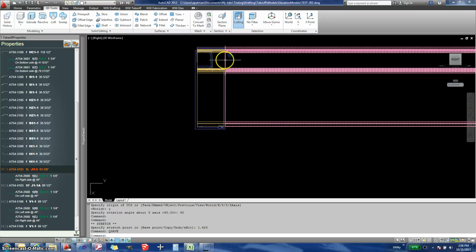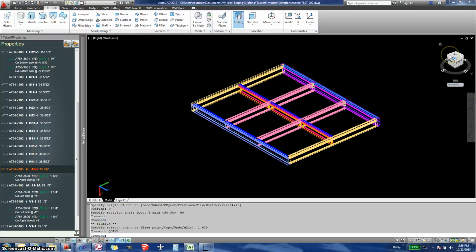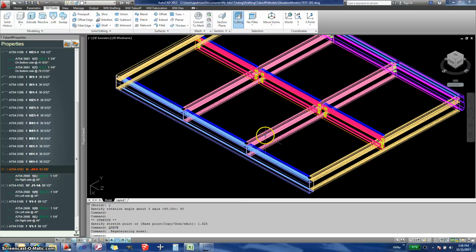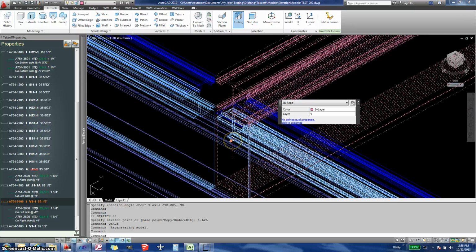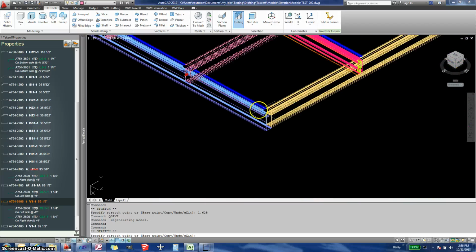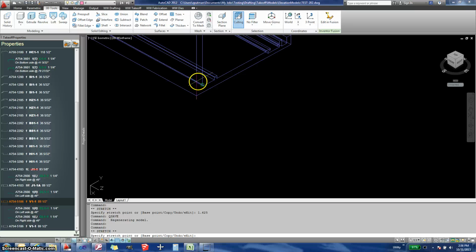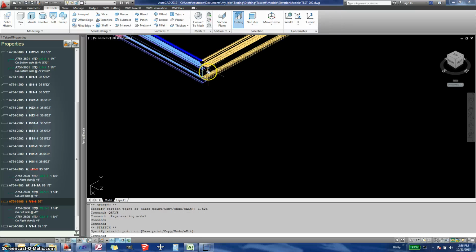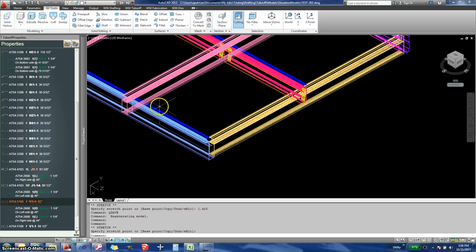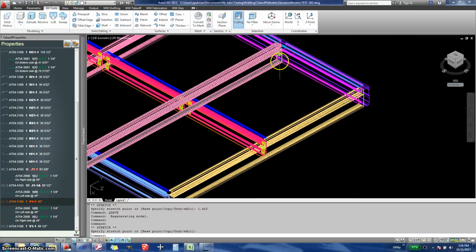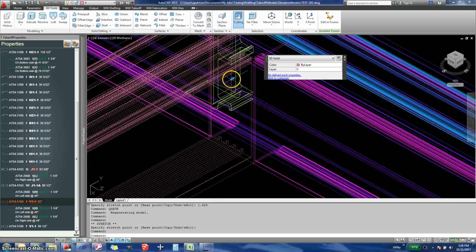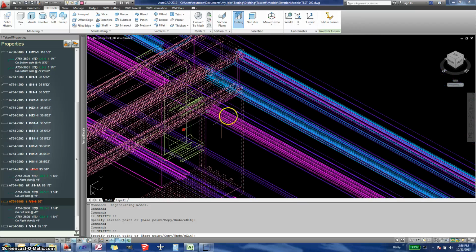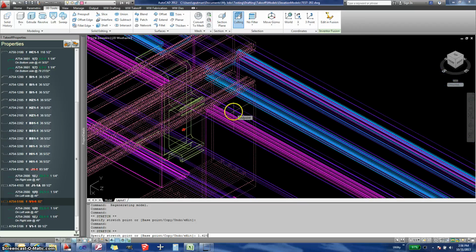Now I could change multiple at once. Actually, let me show you what it's like. This thing has two intermediate verticals. So I'm going to take one here and do the same change. Grab the grip at the bottom, and I'll snap to the bottom of the sill can here. Notice how I don't have to be in the same plane. It automatically knows that you don't want to skew this vertical or anything like that. It simply makes it longer. Do the same thing on the top, like that. And using my ortho, my 1 5/8.